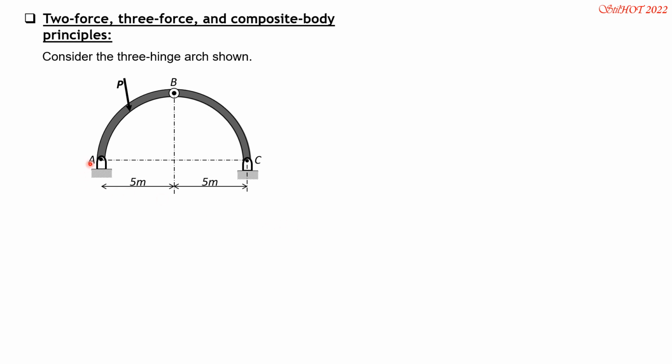So that means 3 per free body diagram. Since there are 6 unknowns all in all, and there are 2 free body diagrams, this structure can be analyzed with ease because 2 times 3 is 6, and there are 6 unknowns here. So we can manage to analyze this.